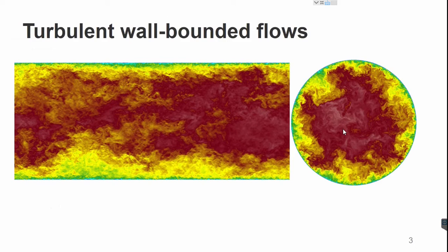So, why are we studying turbulent pipe flows? If pipes are such a simple geometry, it's just a cylinder. And we're still studying this problem because it's really hard to understand, because we have a chaotic, unsteady, anisotropic, and inhomogeneous flow. And this is when we have constant flow rates. This problem becomes more difficult when we have unsteady flow rates, which means that we're changing the velocity of the flow.